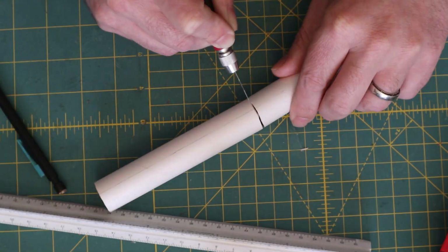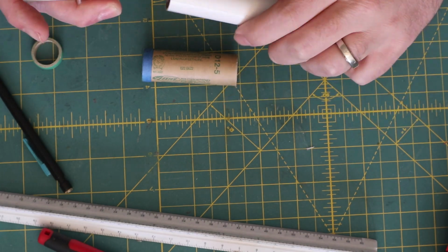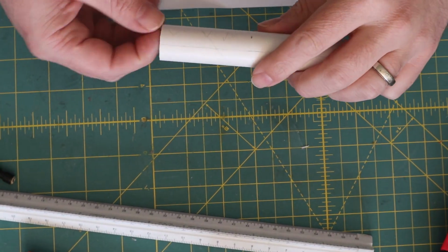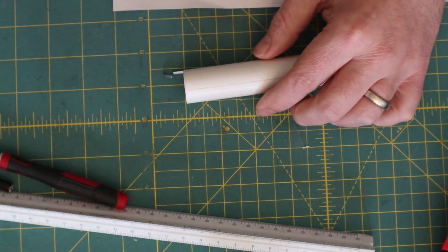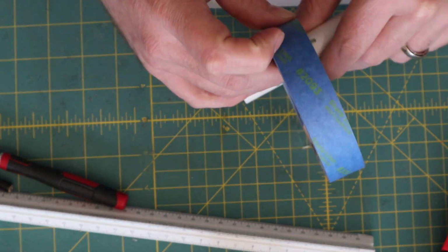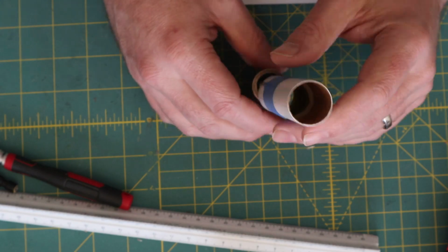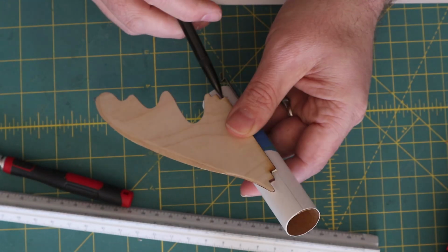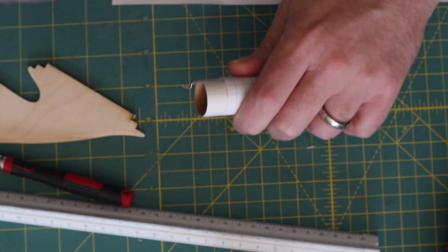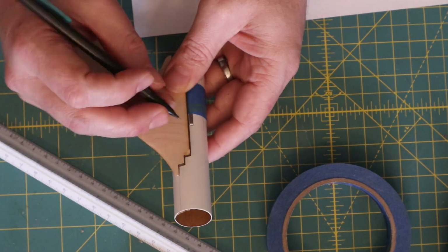We're going to go ahead and start making the motor mount and fin can. So we'll glue in a centering ring to transfer all the force from the motor to the airframe. We'll put a retention clip in, a couple layers of masking tape to hold that down, but still have some spring. Now what we want to do is put the shock cord around the body.